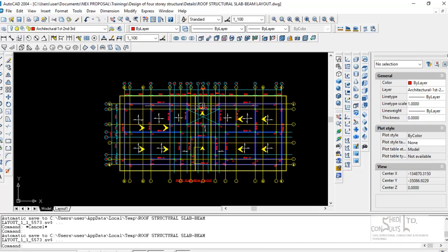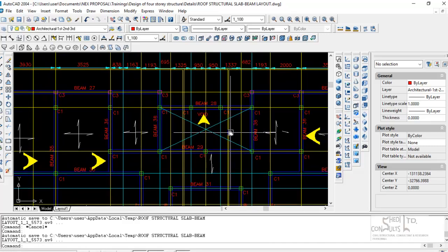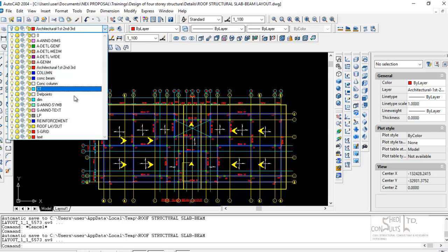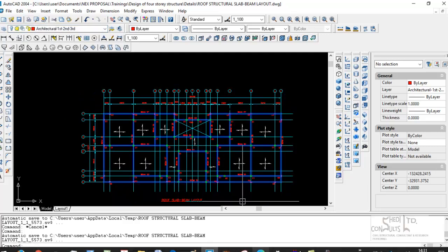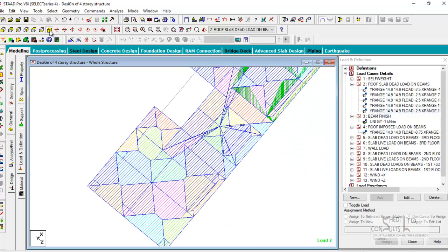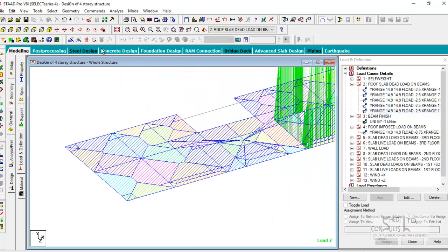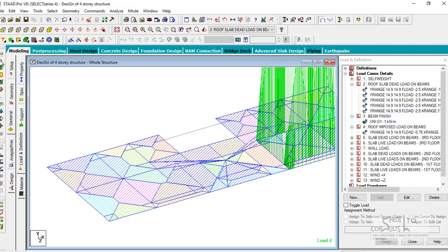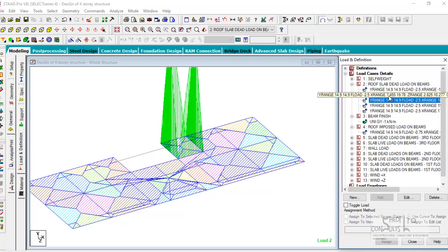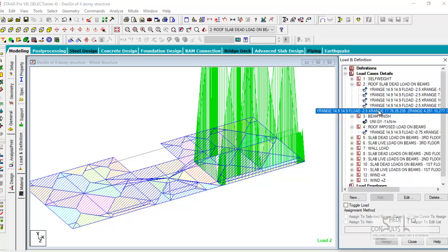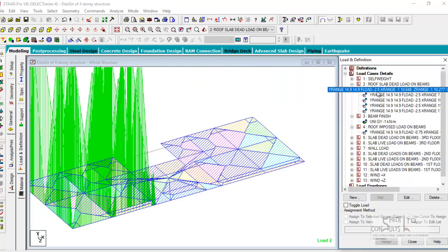We've corrected this error. So these are the type of quality assurance checks you will carry out in your engineering analysis before you perform any analysis, to make sure that your structural design is accurate, is indicative of the load pattern, philosophy, structural modeling stiffnesses, and so on, support restraints, etc., so that you do not have any errors. So the dead load on the slab, on the roof beams have been broken down correctly to represent exactly the locations where they actually apply.